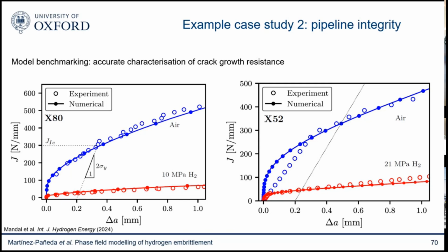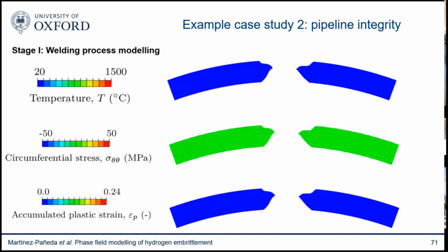Because, of course, fracture mechanics works well, and at some point you say, Emilio, why don't I just use fracture mechanics to design my pipes? Well, the problem is that fracture mechanics works for a homogeneous material. But here you don't have a homogeneous material because you have a hydrogen distribution within your pipe, and this is making your toughness dependent on the hydrogen concentration. So you need something more sophisticated than fracture mechanics.